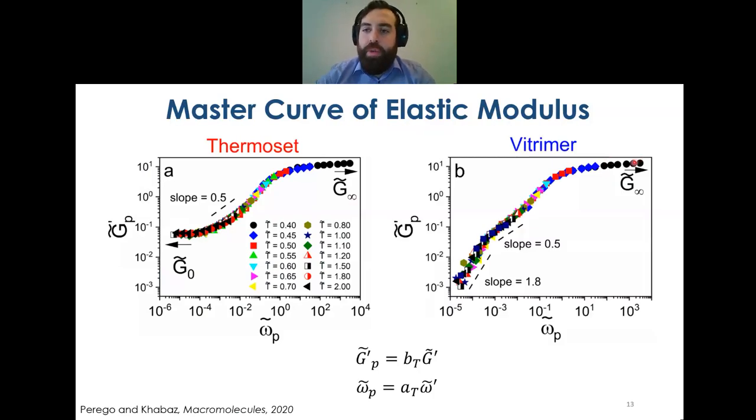However, for the vitrimer, as I said, we can still see the glassy and the transition regime, but after a small rubbery plateau, this shoulder, the liquid regime happens, and this is indeed what we would expect for these dynamic networks. Now, the rubbery plateau is not as extended as we would like it to be, but the reason is that at this reference temperature, the time scale of the exchangeable bonds coincides with the time scale of the external deformation, meaning that this rubbery plateau turned out to be more like a shoulder-like transition. However, the change in slope clearly indicates a transition region from a rubbery to a viscoelastic liquid regime.